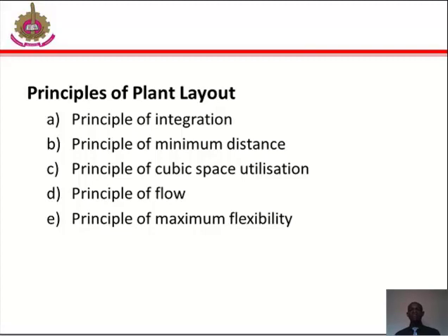Under principle of cubic space utilization, a good layout is one that utilizes both horizontal and vertical space. It is not enough if only the floor space is utilized optimally, but the third dimension, that is the height, is also to be utilized effectively.